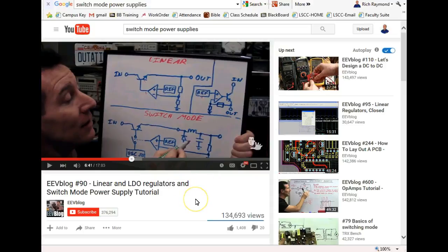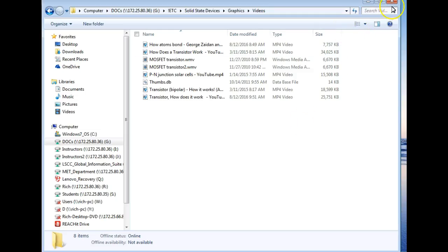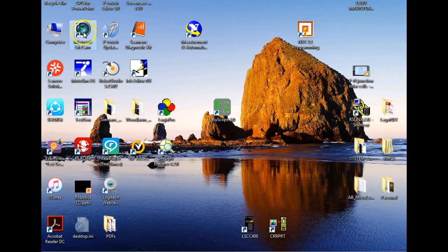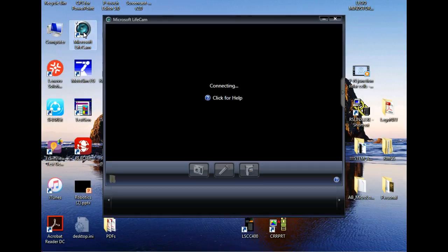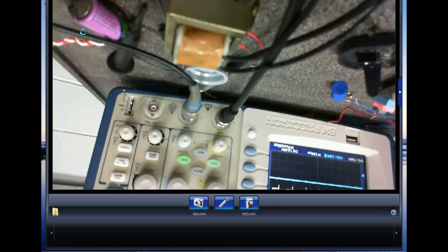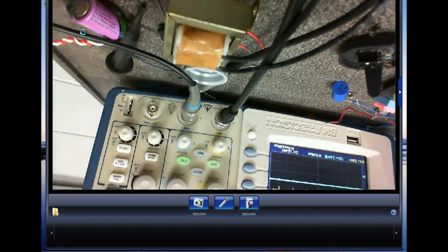So what I've done is I've kind of played around with this. So y'all come up here and I'll show y'all this power supply up here. It'd be better if you see it. Now what I'm doing is I'm faking my oscillator. So this is what we would get out of the oscillator. So we come in and do what? We rectify it, filter it, and oscillate. Oscillate means we take a DC waveform and convert it into some type of pulsing.